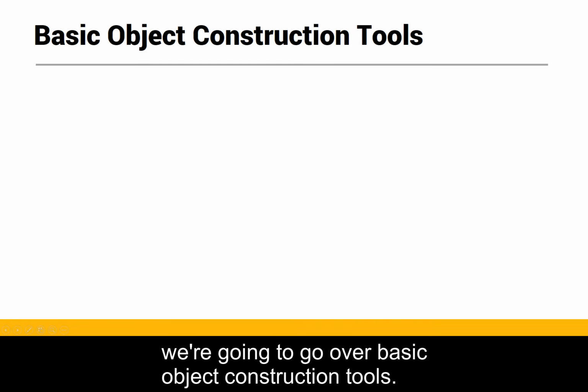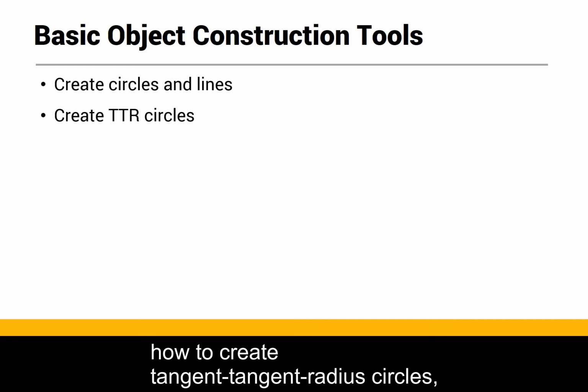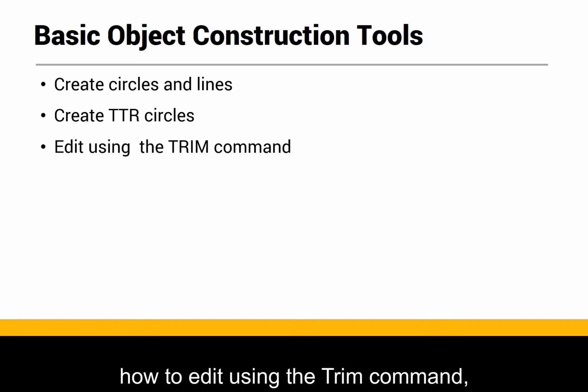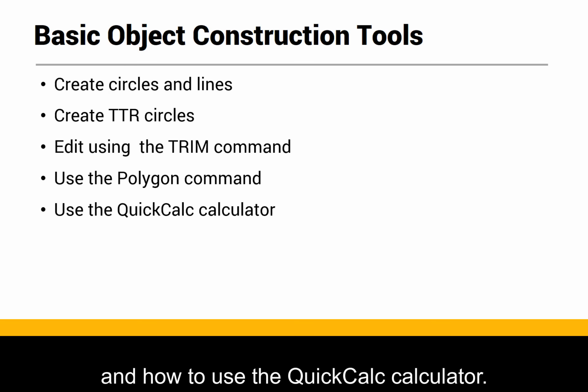In this lesson, we're going to go over basic object construction tools. We're going to learn how to create circles and lines, how to create tangent radius circles, how to edit using the trim command, how to use the polygon command, and how to use the quick calc calculator.